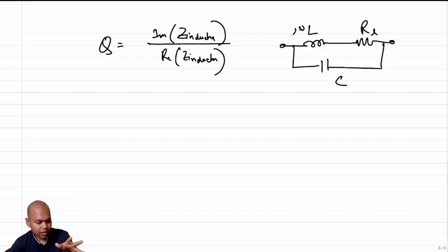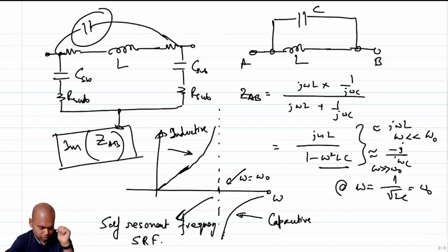So the crux of the matter is that you design an inductor, you find out its imaginary part, you find out its real part, and you plot its impedance, and then see where the self-resonant frequency is, or you plot the Q and find out the sweetest point to operate an inductor at, and then you keep tweaking your design, right? If, for example, you see your self-resonant frequency is lower than anticipated, what design handles are you going to use? So what is the cause of self-resonant frequency?